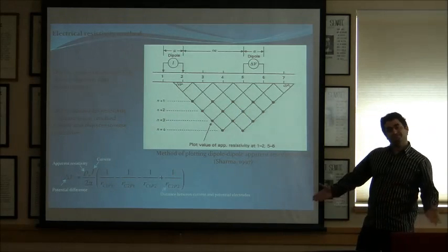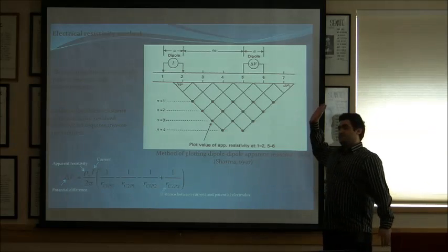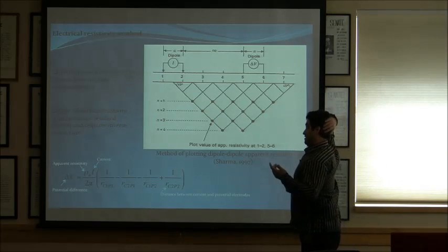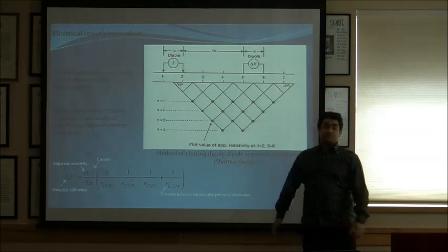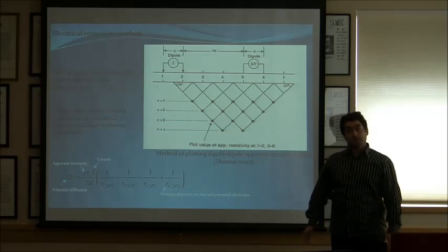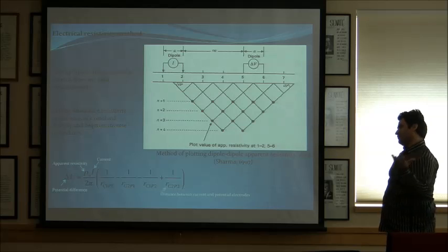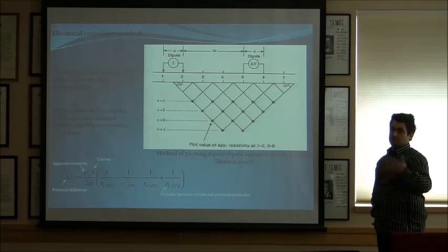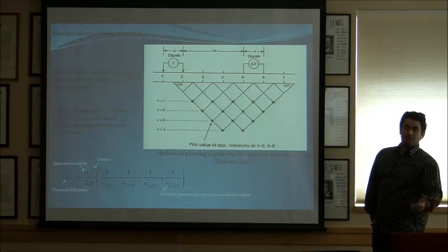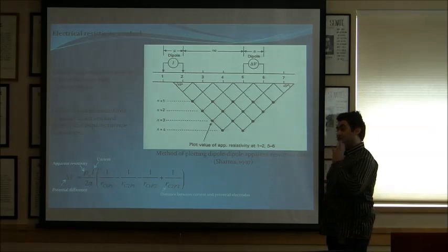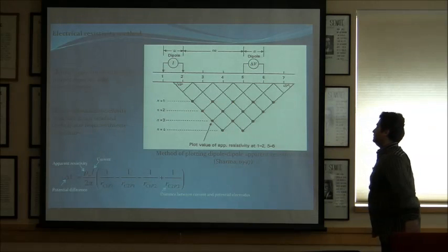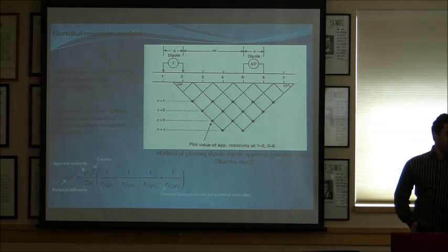In fact, there is an alternative geophysical method called frequency domain electromagnetic. That can work in any terrain. So usually people now start to substitute resistivity with frequency domain electromagnetic, especially in very resistive environments.